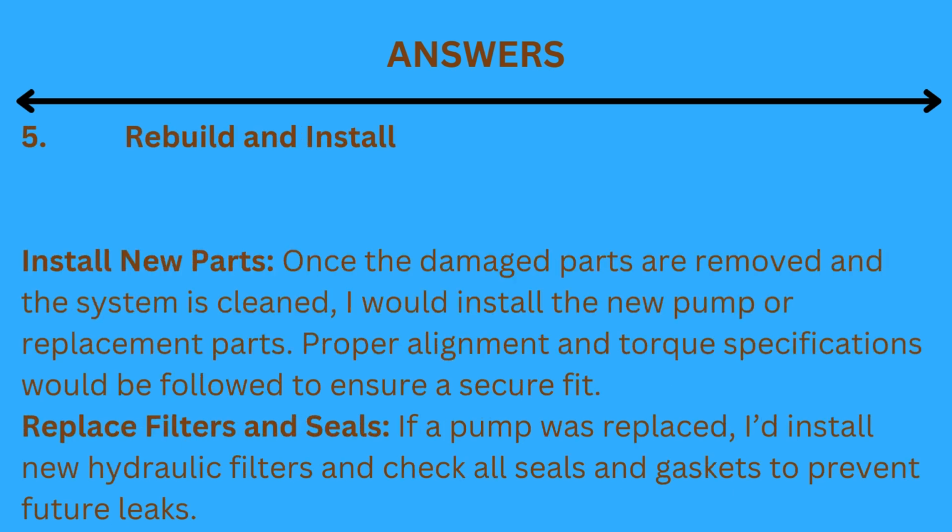5. Rebuild and install. Install new parts. Once the damaged parts are removed and the system is cleaned, I would install the new pump or replacement parts. Proper alignment and torque specifications would be followed to ensure a secure fit.